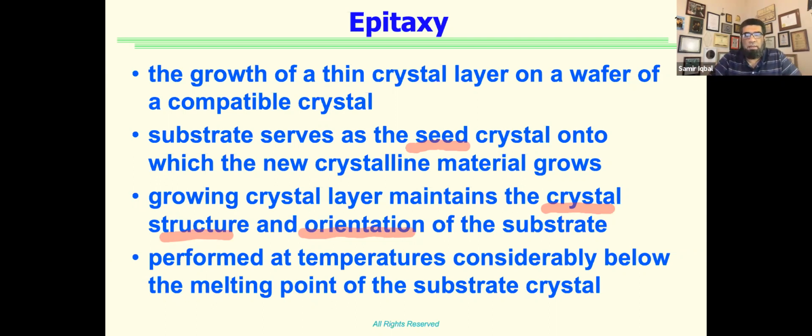Okay, how is it done? We do a process called chemical vapor deposition. I'll get into that, but there's another thing I want to talk about: we can have many different variations of a material when we do epitaxy. When we do the Czochralski method, you can have one material in the molten pot, and maybe you can add some dopant into that, right? But you cannot have variation in the structure or variation in the material. Let me show you the next slide, and then this will become clear.